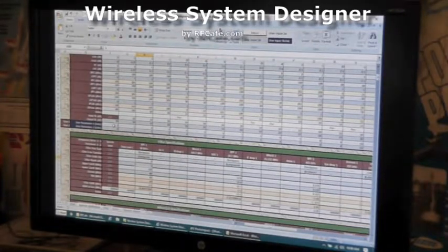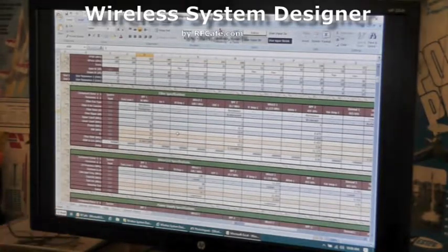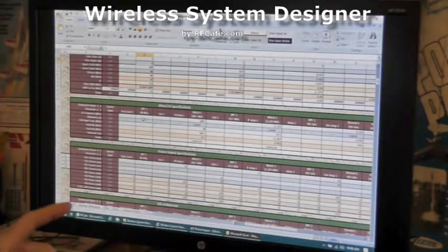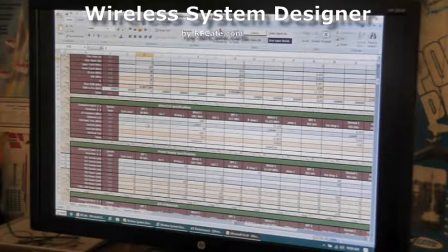I also provide a couple of areas for you to define your own set of parameters, and there's a place for formulas that reference those parameters farther down the spreadsheet. In the mixer and LO specifications, you can put a frequency translation in every stage if you want. Not much chance of doing that, but you can do it if you want. And here, the center frequency of the LO, you can select whether you want the upper or lower sideband.